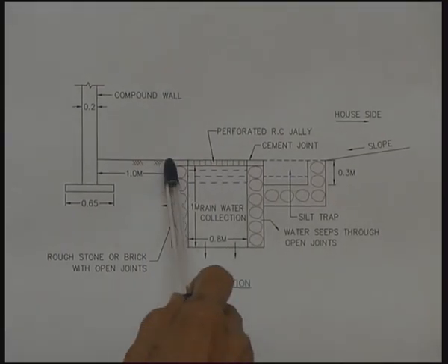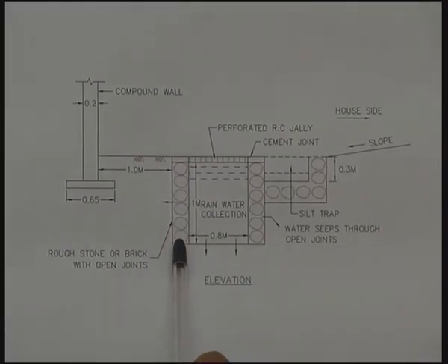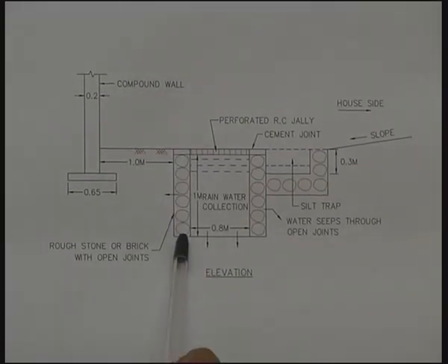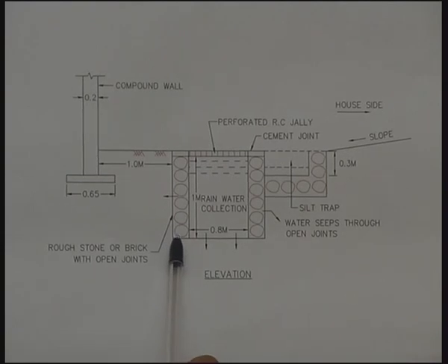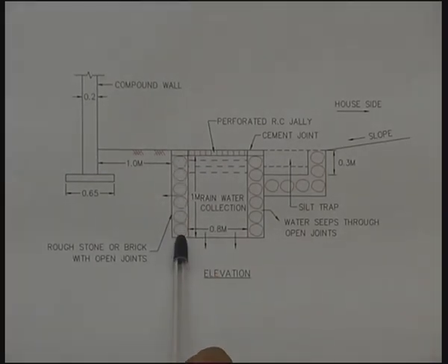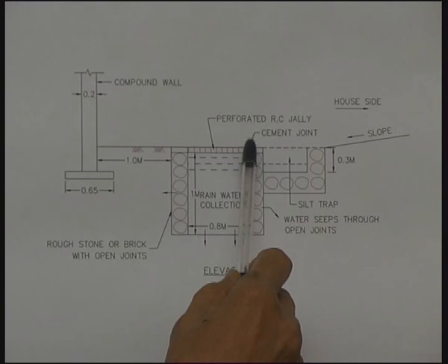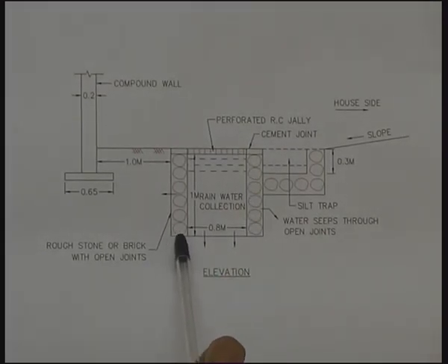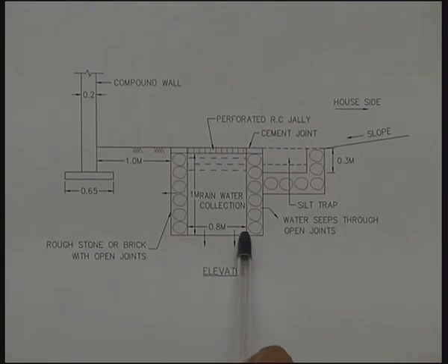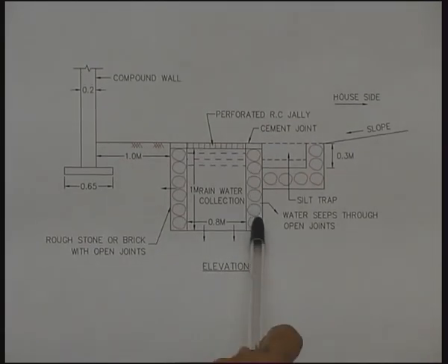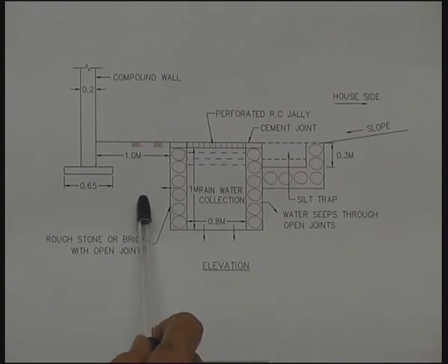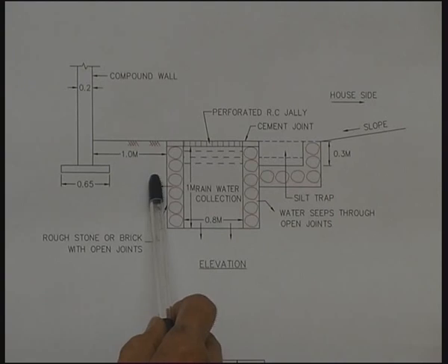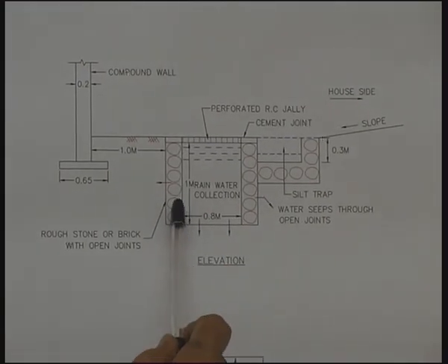and in order to retain the sides of the trench, rough stone dry packing can be done, something like a revetment, a vertical rough stone dry packing. If the soils are loose, it can even have a slight slope, and there is no revetment at the bottom. This revetment is only intended to hold the soils so that they may not cave into the trench, because this